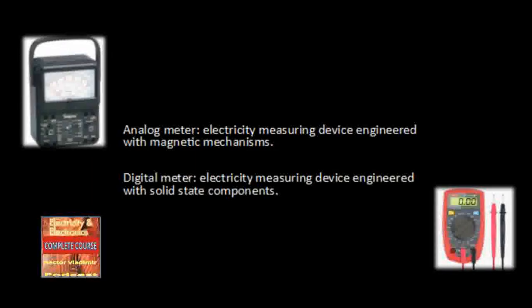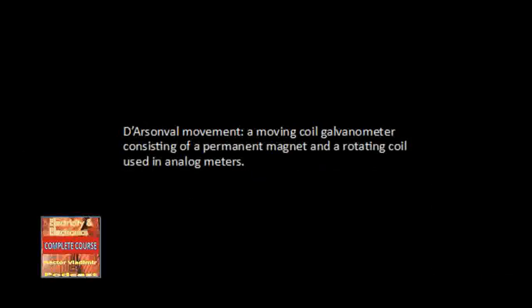Think of an electrical meter as an electronic ruler that is used to measure electrical quantities such as voltage, current, and resistance. The meters you will be using come in two formats. There are analog meters and digital meters. Analog meters, discussed first in this chapter, use a scale with continuous variable values. Digital meters give values in discrete amounts using the units 0 through 9. Digital meters are discussed later in the chapter.